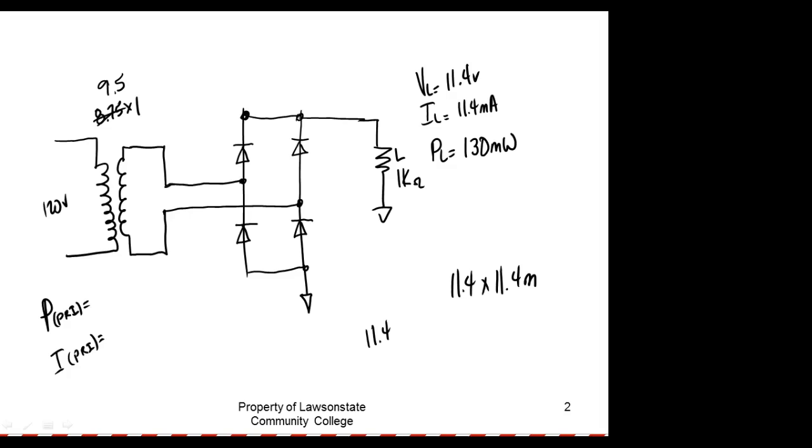Okay, so what's the power in the transformer? What's the power in the primary? Take a guess. The same. The transformer doesn't change power. So it's 130 milliwatts. It'll be a little higher because of transformer losses. Okay, so what's the current in the primary?